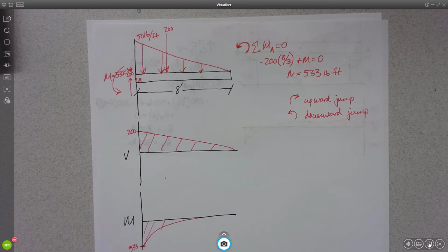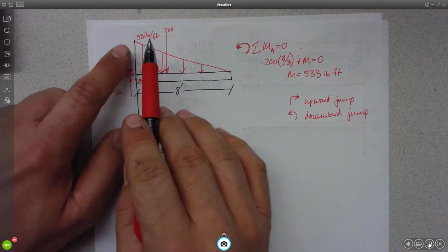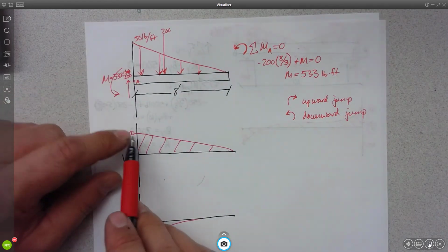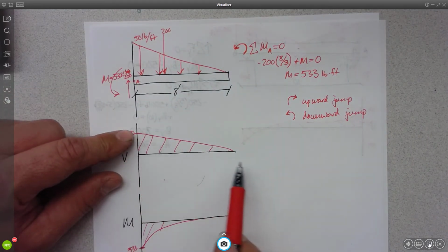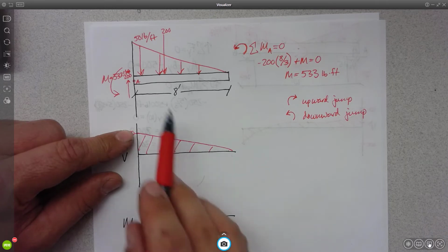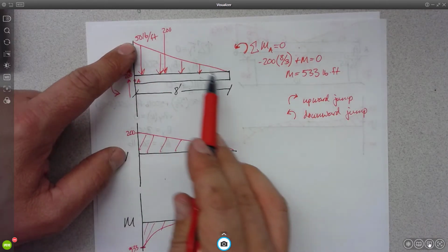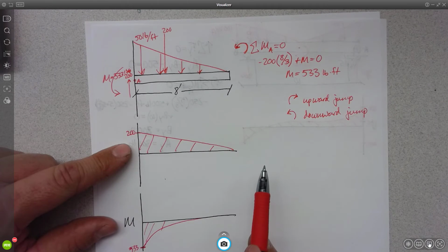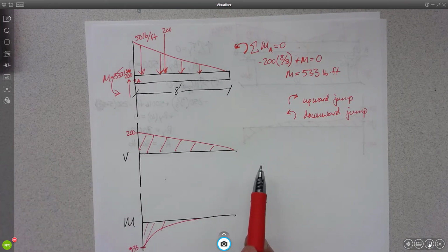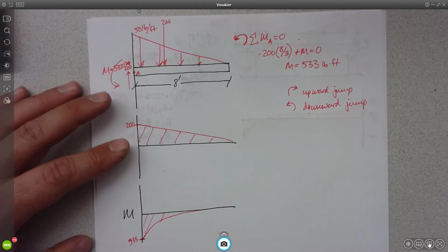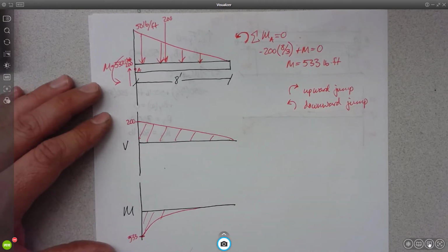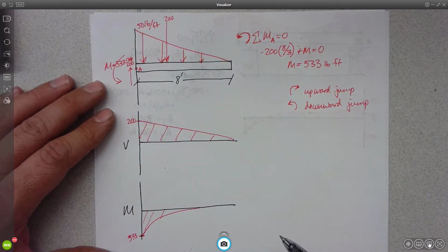If it would have been a straight, like, distributed load, then that would have been right. So I looked at this and said, my slope is negative and decreasingly negative, right? My slope is very negative and decreasingly negative, and then I drew a straight line. That's not right at all, is it? Whew. Thank you for calling me on my egregious error here. Because don't you just look at the distributed load, take the integral of that?